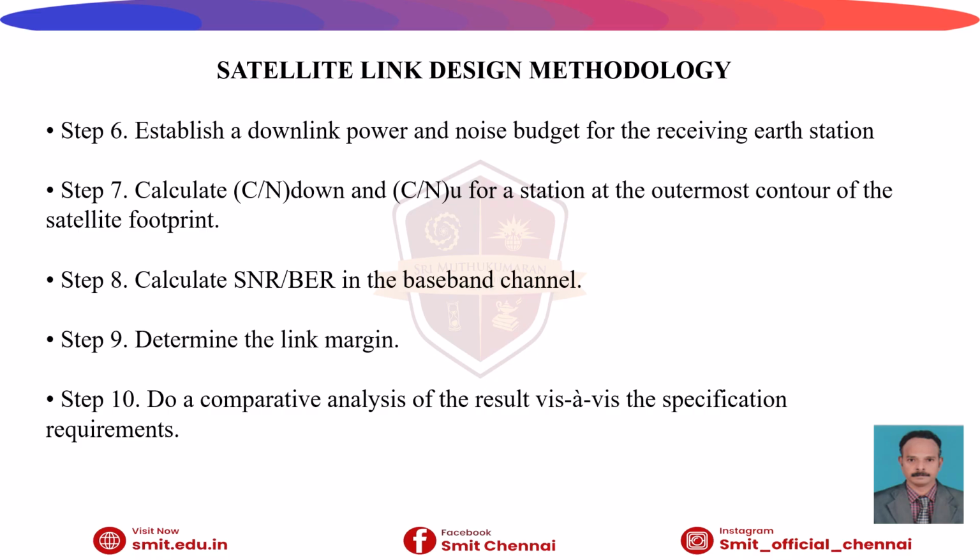Similarly, the next important parameter is the bit error rate. Bit error rate is the measurement of transmission errors. It should be as minimum as possible. The desired bit error rates have some typical values. For example, if it is voice, it should be 10 power minus 3. If it is data, it should be 10 power minus 6. Higher quality digital data may have 10 power minus.